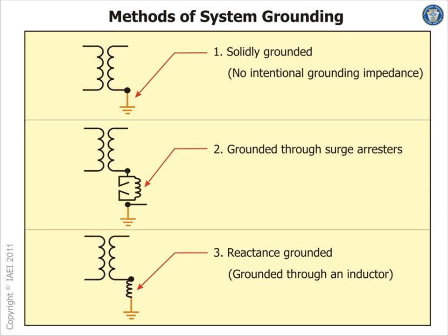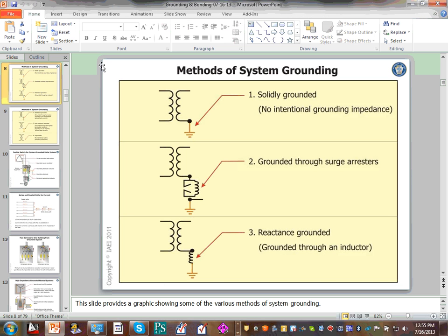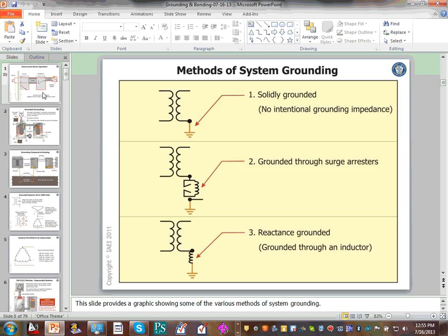Any comments, guys, before we go talk about grounding the system? The advantage of grounding the system is getting you a voltage and stabilizing the voltage to the ground and getting rid of the transient. Transient coming out of lightning hitting the transmission line, or an air handling unit switching on and off and making transient into your power system. So I thought I'm going to start with these, if you guys don't mind.